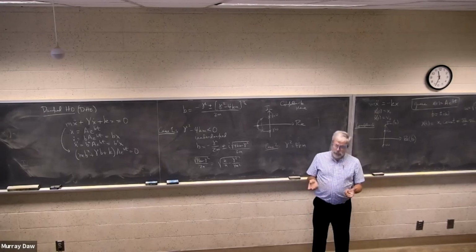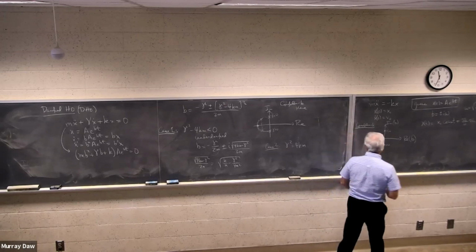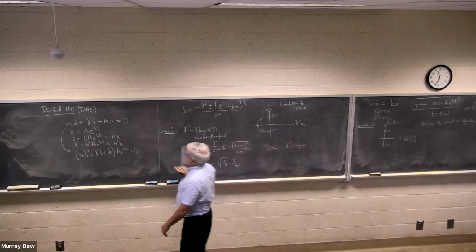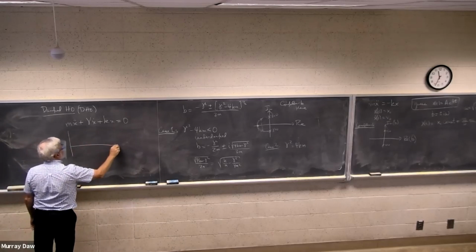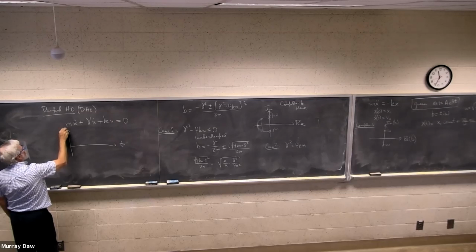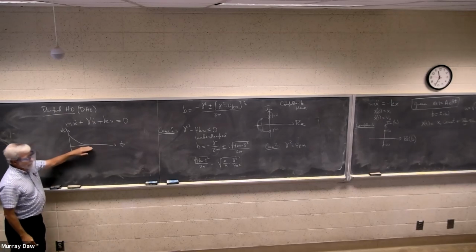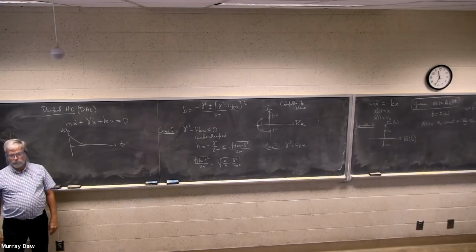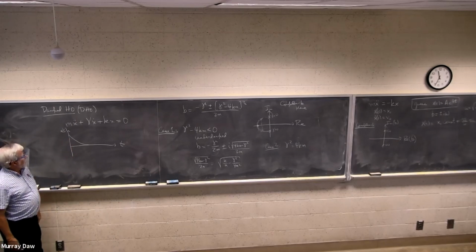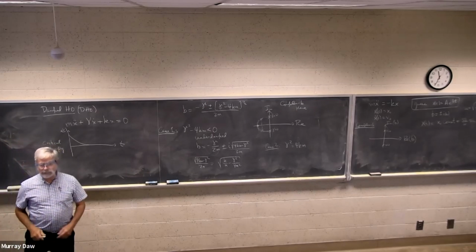Okay, but now we've raised the damping enough that we get critical damping. There's no oscillation left. And so the system will behave, no oscillation. So x of t, you get a complete solution, it just does this. Asymptotically approaches. It never really reaches it, but it does not oscillate. So this is critical damping. There's one value of the damping coefficient that will cause it to be critically damped.